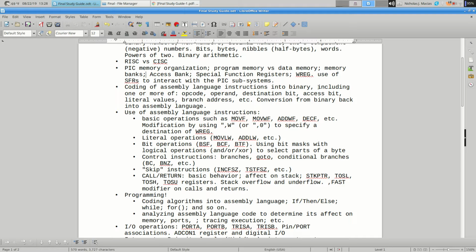All right, so there's a stack pointer which tells you basically how many things are on the stack, and there's 3 registers that show you the value on the top of the stack. Top of stack, upper, high, and low. If you push too many things, you get an overflow. If you try to pop too many things, you get an underflow.